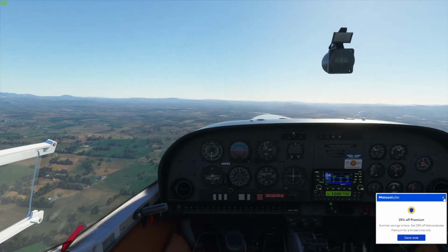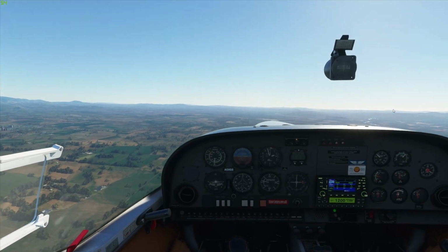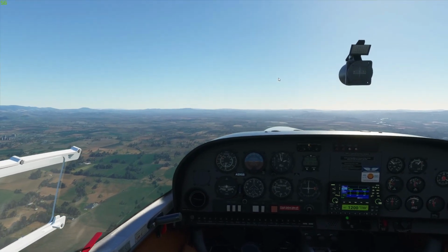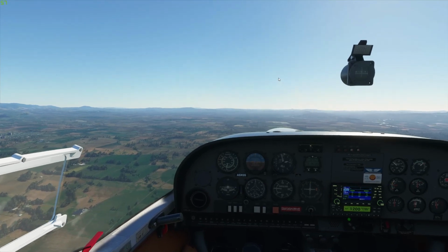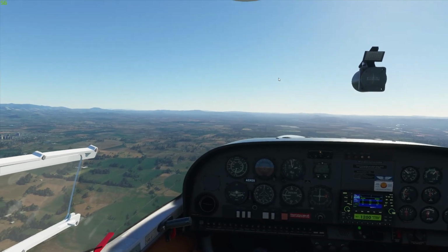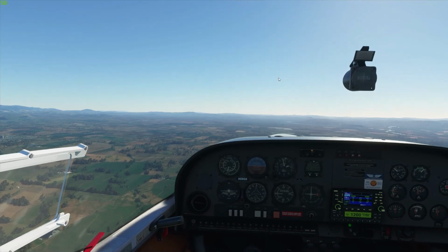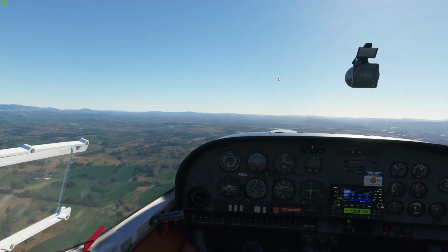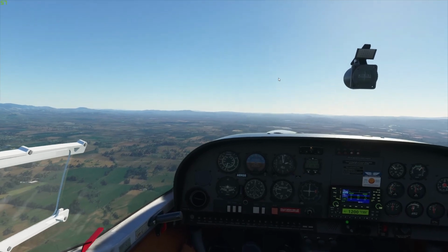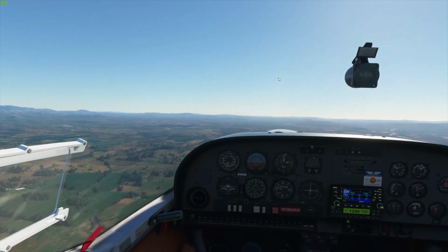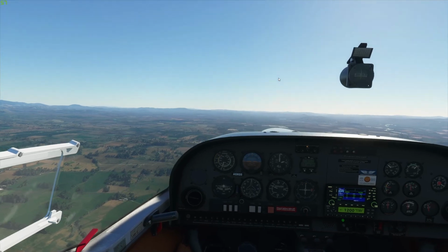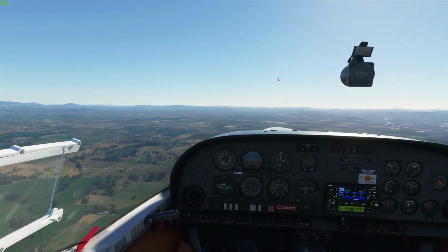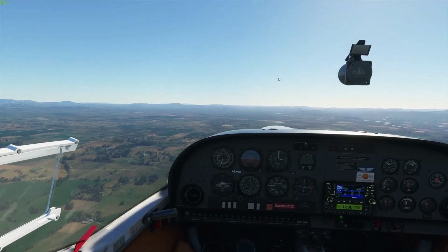The idea is, without changing anything, I'm going to just increase the nose attitude until we lose about 10 knots of airspeed, and then just let go of the stick and see what happens. We should get an oscillation, because the aircraft is trimmed for 105 knots or so, its cruise power setting, although we're only getting about 90 at the moment, so it seems about right.